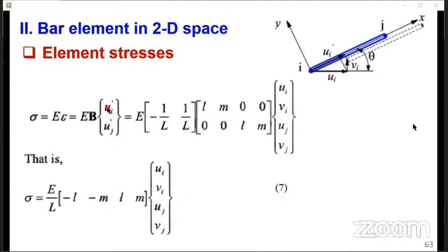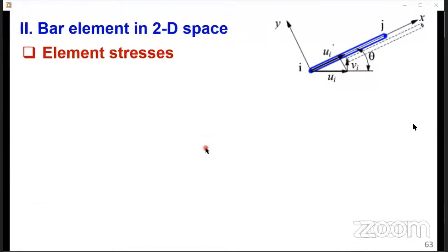In terms of stress for the element, we are talking of elements, not the global element. There is no stress that will occur in the y coordinates, the small y. That's why we are just concerned with u_i and u_j, the axial components. So don't ask yourself why our matrix has condensed. It's still our matrix that we are using.